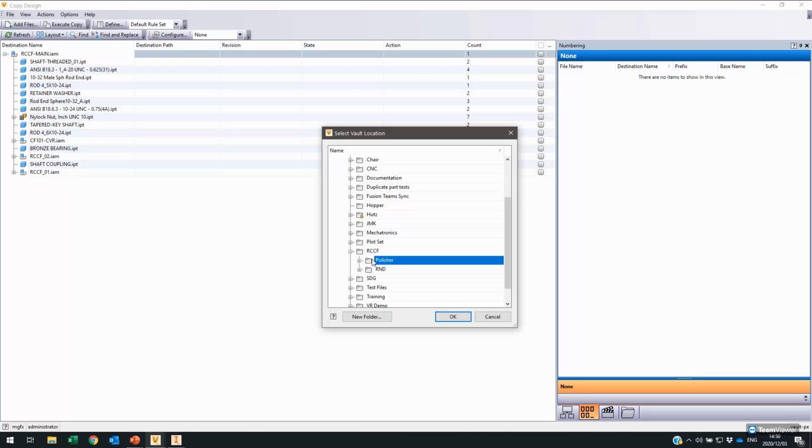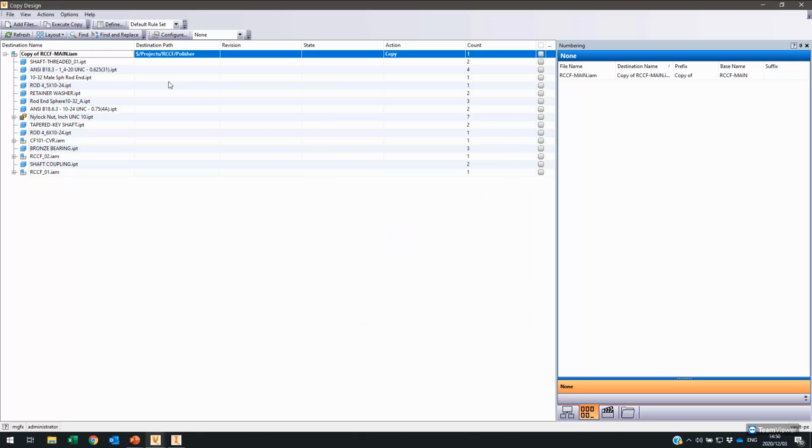So this maybe smooths over the concrete, but I want to create one of these that polishes the concrete. So new product development, I'm grabbing this old design and copying that folder, copying the main assembly into that new folder. Now this main assembly may reuse a lot of information, but what I want to do here is copy what I'm going to change.